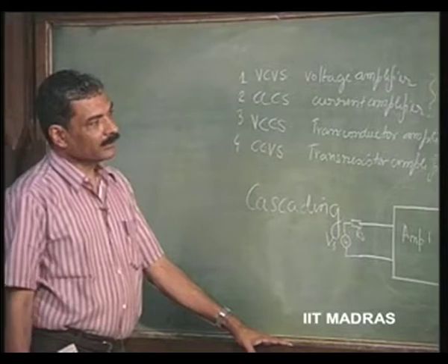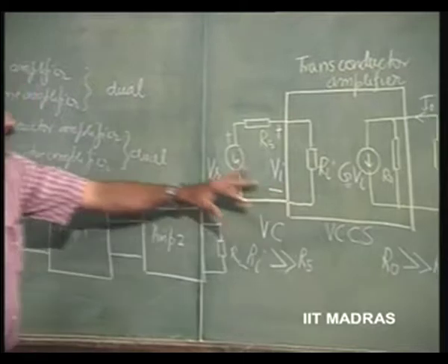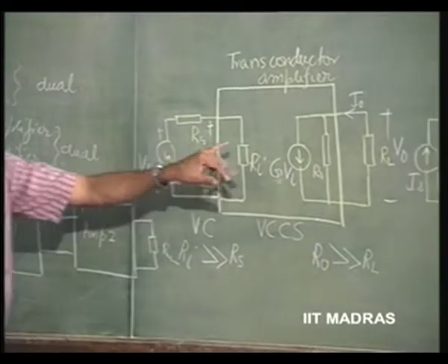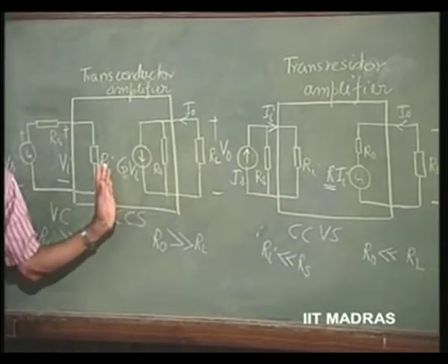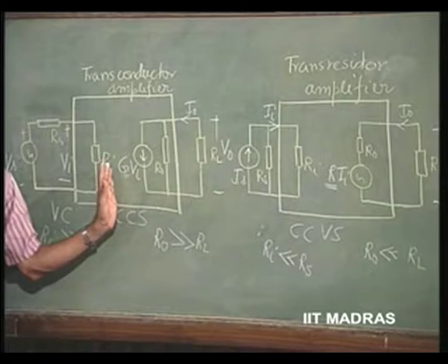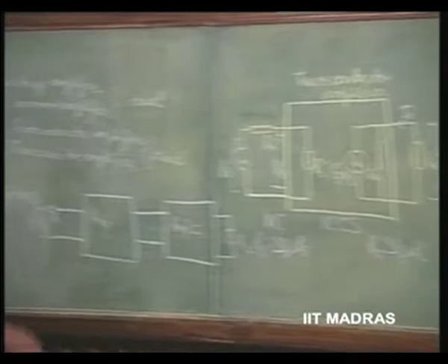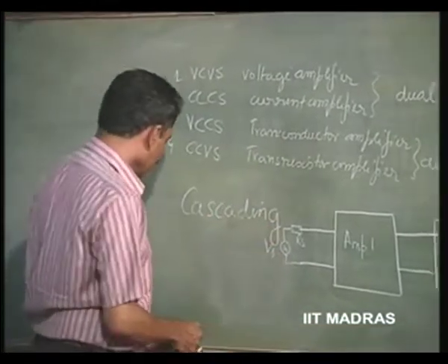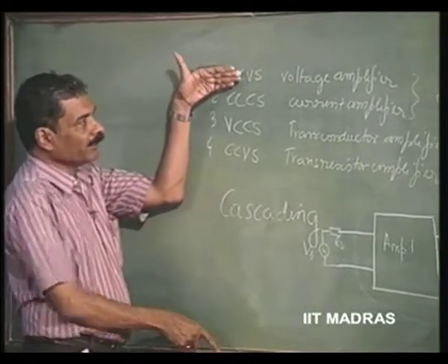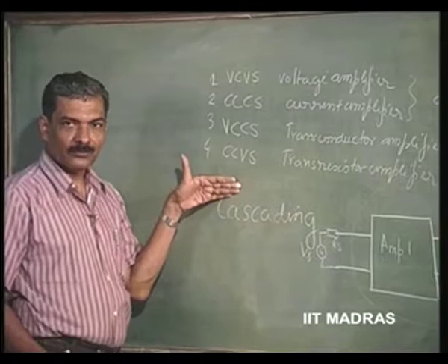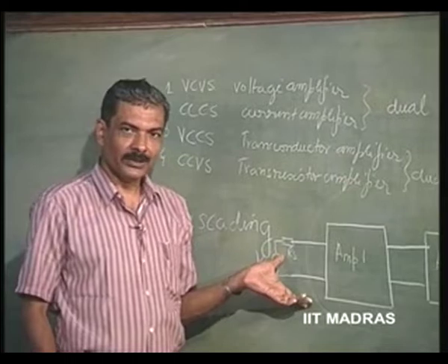So, now let us try to evaluate, for example, the voltage amplification factor here, and current amplification factor here as well as here, because these are two different types where the voltage amplification and current amplification have not directly made an appearance. Right. So, after that we will cascade the non-ideal amplifiers together. So, these non-ideal amplifiers again could be represented in any one of the 4, and they will be called a particular type depending upon what kind of source and load we have.